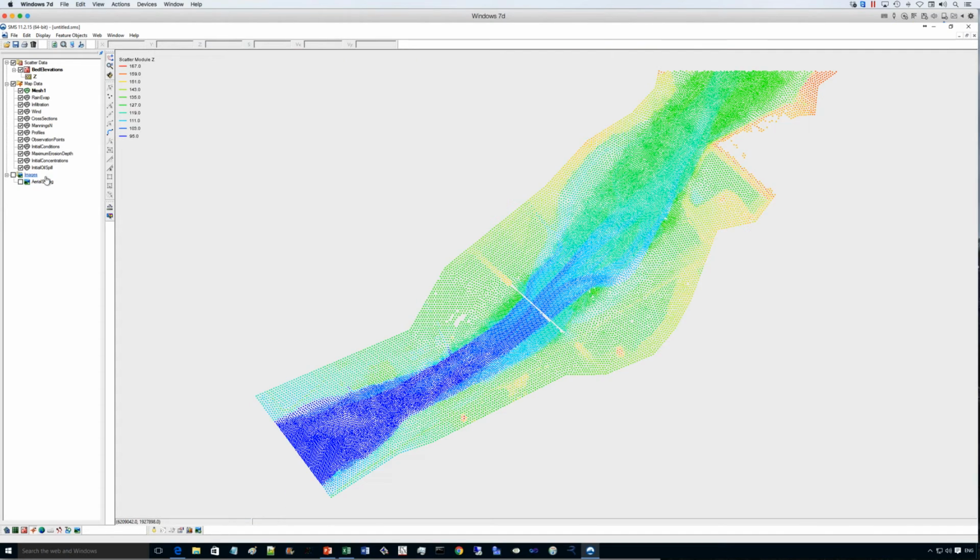Now I'm turning that off because I want to enter the boundary polygon, and I will do that without the image in the background. It's easier for this particular case. So I'm entering this polyline here, another polyline for the inflow boundary, this lower solid boundary here, and lastly the downstream boundary here.